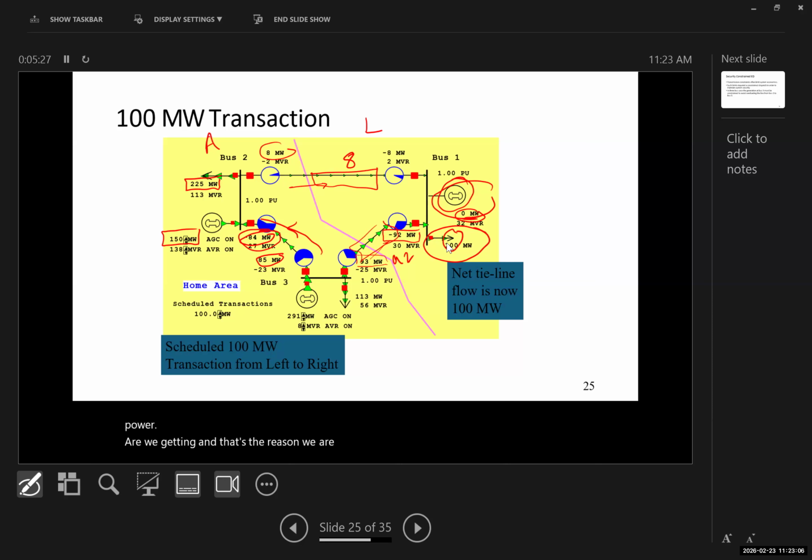We are not mentioning the reactive power because, again, we were going to have power factor correctors at each end to correct all of that. We want to see how much real power, how much useful power we can transfer. And in the exam as well, we're going to just focus on the real power part because we want to know how much work we're going to do with that real power.